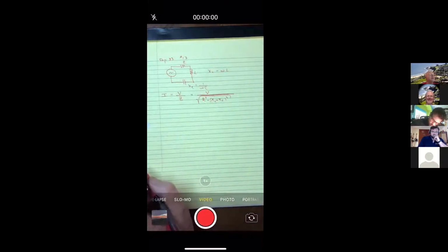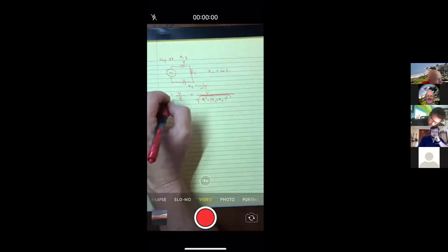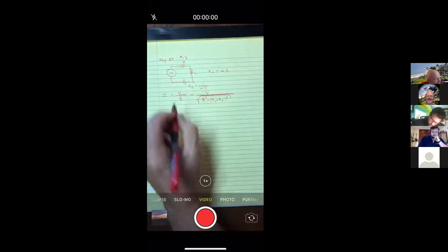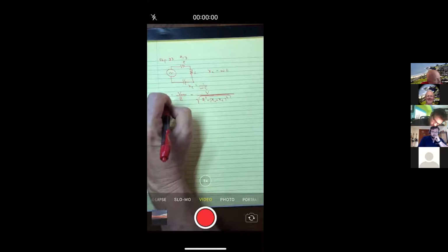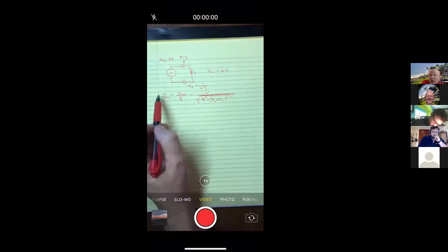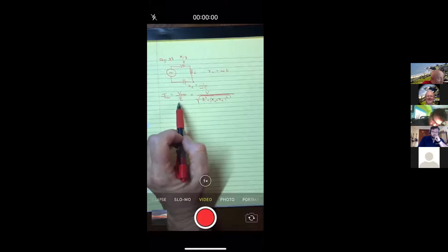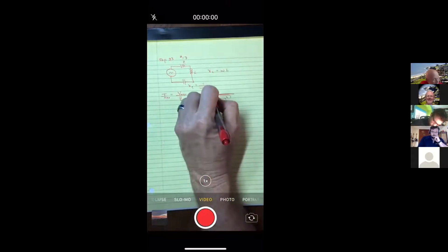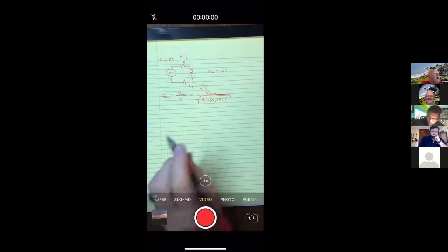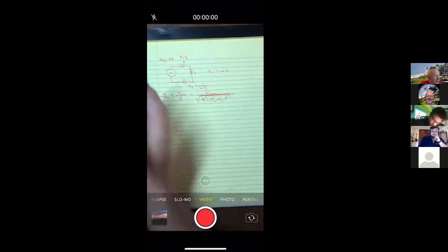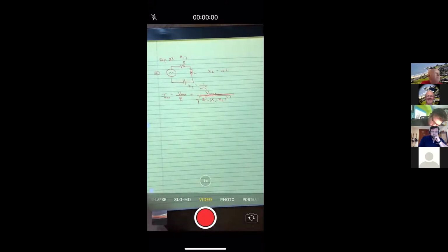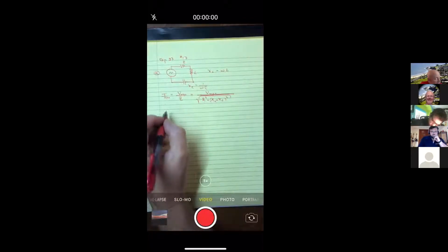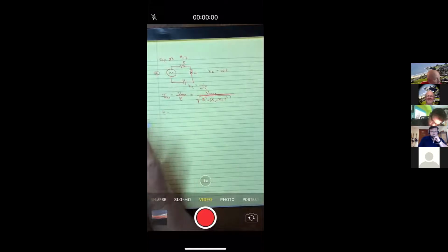In this case, they give us the peak voltage. So maybe I should put here, if you put in maximum voltage, this will give you maximum current. The same equation applies, by the way, for RMS if you wanted to do RMS. But since our question, or at least part A, I haven't really gone on to B yet, clearly says calculate the required peak voltage in order to get this peak current. So let me just calculate the impedance here.